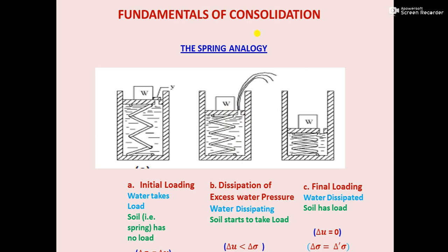In case of sand, which is highly permeable, as soon as the water takes the load, because of the permeability, that means if this hole is much bigger over here, then very fast this water will go out of this tank, right? And complete load will be taken up by this spring. So that is actually happening to sand.